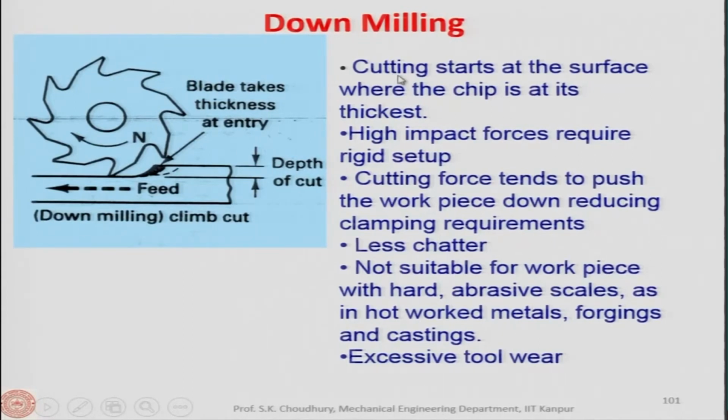Now, the cutting starts at the surface where the chip is at its thickest. That means, it starts from the maximum chip thickness, it grabs and then it goes to the minimum. So, it is just the other way around.